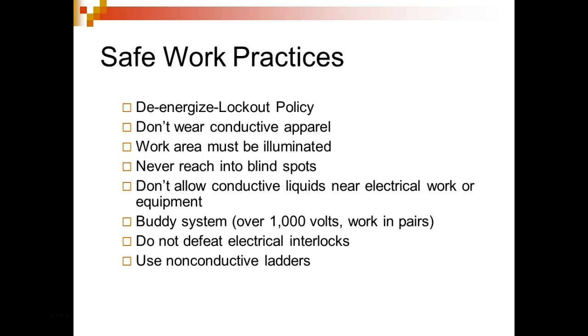Use the buddy system. At US Steel, it was 500 bucks. That was their policy. But I don't ever remember working at US Steel by myself. The whole time I was an electronic repairman out there, I don't ever remember going out and working on something by myself. So it was always what? Two. A buddy system over 1,000 volts works in what? Pairs. Do not defeat electrical interlocks and use non-conductive ladders.